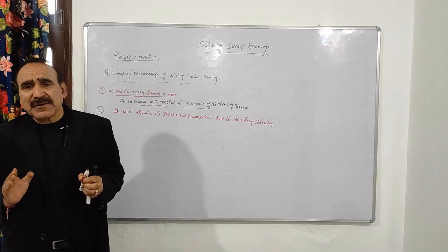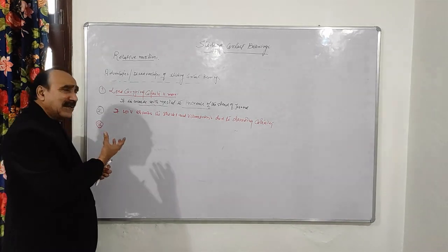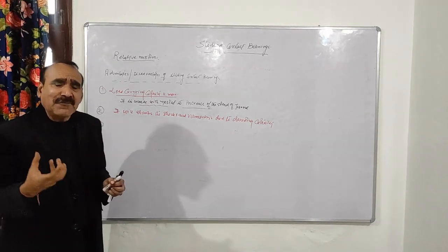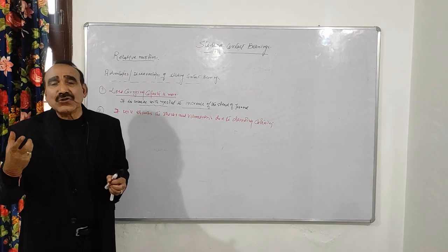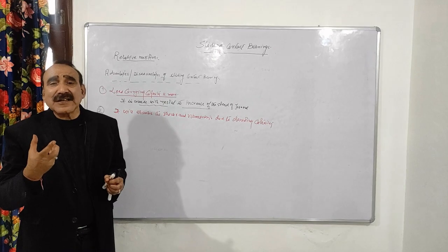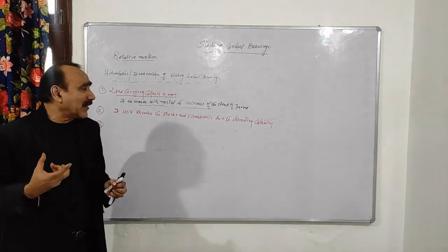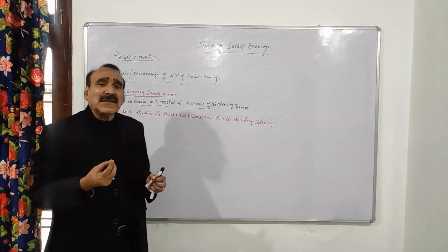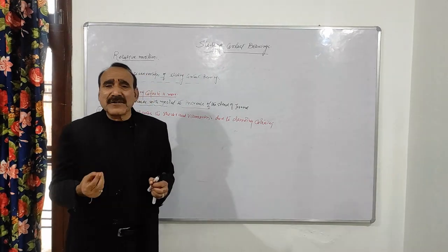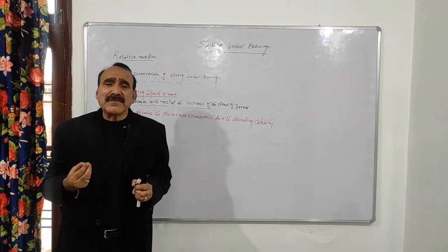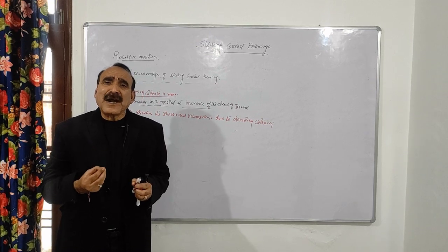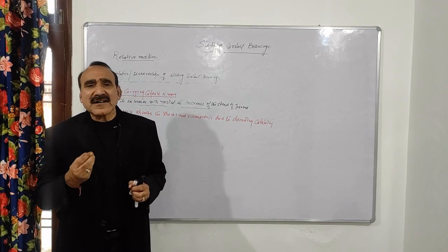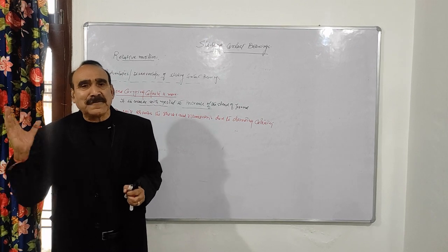So the operation of this sliding contact bearing is noiseless. So this is also one of the advantages, that in hydrodynamic bearing or in journal bearing, there is no metal to metal contact when it is running at full operative speed.